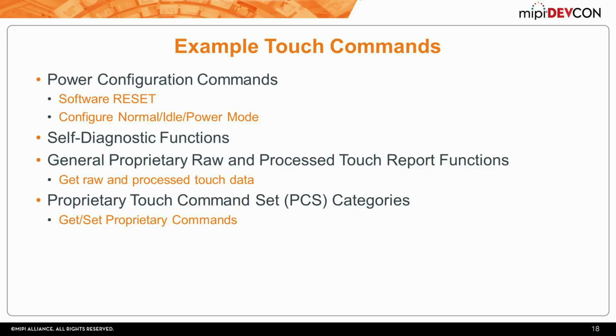So being able to tell the device what mode you want it to be in and what behavior you're expecting, which can be useful for solutions where they're trying to be able to do power management or other controls. Self-diagnostic functions. So I don't have to know some special way to get a touch controller or an AFE to actually tell me if my touchscreen is still behaving correctly or if there's some problem. I can issue a standard command. It can run a sequence of diagnostics and basically report back.